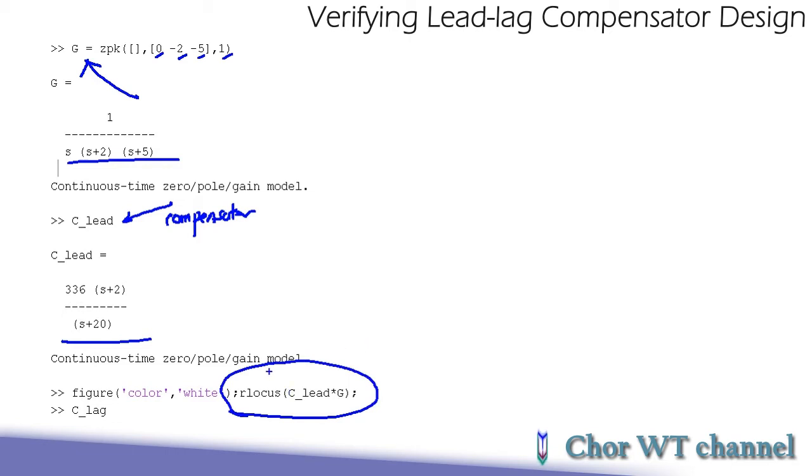The root locus will be of the system with the compensator multiplied by the transfer function G. In this example, we will omit the Lag Compensator's zero and pole because they are chosen in such a way as to minimize the effect on the shape of the root locus. Hence, in our verification, our main objective is to verify that our compensator has been designed correctly.